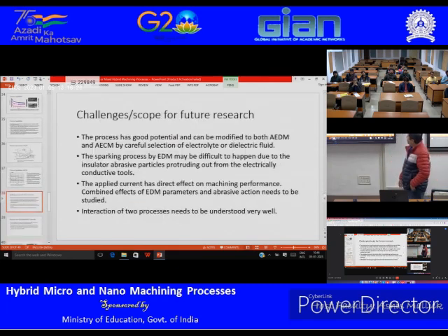Challenges. The process has good potential and it can be modified to both abrasive assisted ECM or abrasive assisted EDM by careful selection of the fluid material, whether you are using dielectric fluid or electrolyte for ECM. The sparking for the EDM can be difficult.